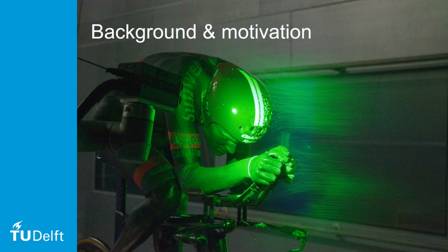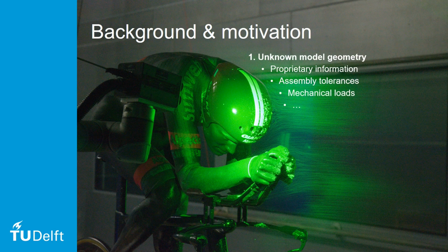So let us start with this photograph of the velocimetry measurement on a full-scale cyclist that we have done in our wind tunnel facilities in Delft. Why should we need a tracer-based interface detection method? Well, in fact, part of the geometry is unknown to us. So in this specific case, we didn't have the geometry files of the bicycle and the helmet, which were not released by the manufacturers. On top of that, we have assembly tolerances from placing the model onto the bike, but also placing the helmet onto the model. This introduces mechanical loads as well, which can result in model deformation. In your case, you may have aerodynamic loads, which also cause a displacement or deformation of your model.